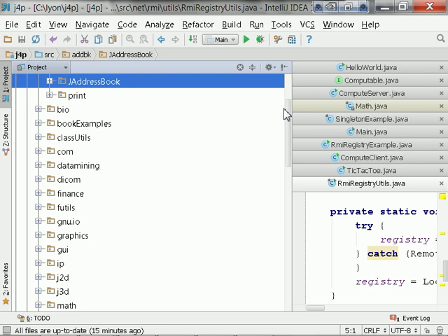COM ports, the serial ports, have been around since the 60s. And the serial port standard started with a 25-pin D-connect. Apple appropriated it when it came out with the Mac and used it for its SCSI interface. Form factor identical. You can plug your RS-232 port right into the motherboard of the Mac Plus or Mac SE, and completely blow it out because it's 10 volts going into a 5-volt input. Because COM ports, RS-232, that's plus minus 10 volts, in fact. And if you think about it, what a bad choice they made. But they had these connectors and they decided to use them.